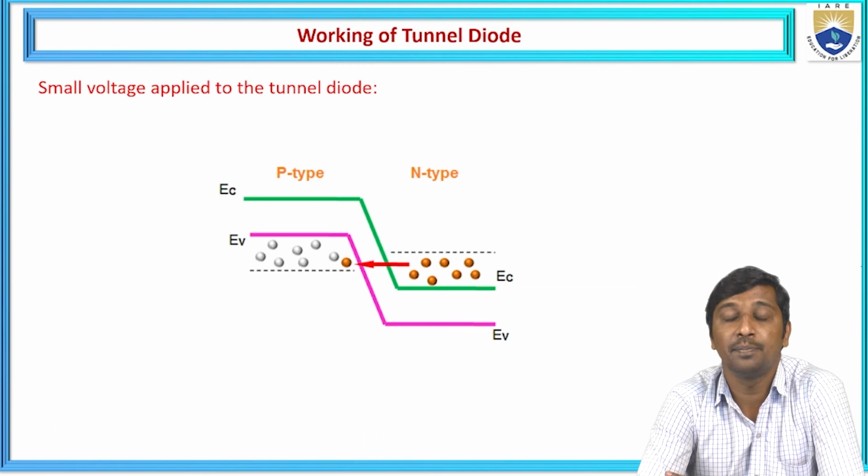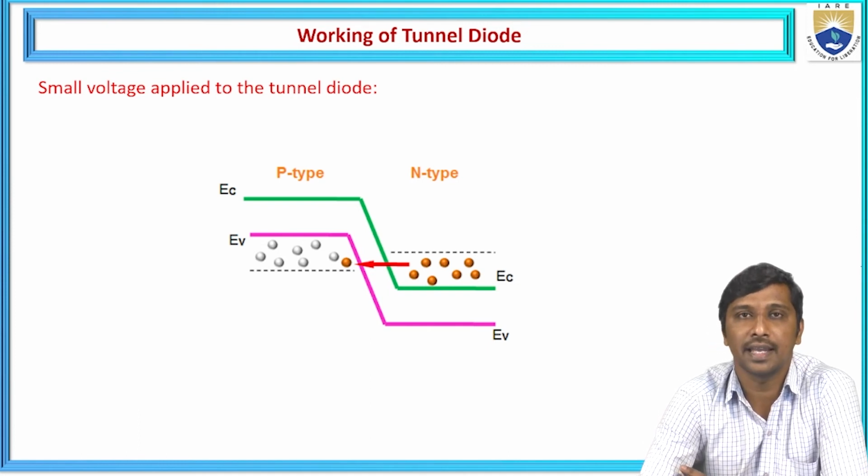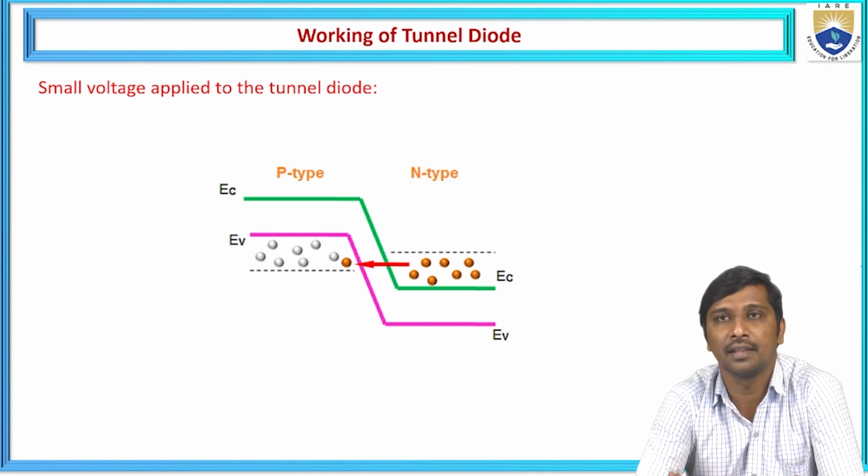happens? The depletion width decreases, hence it allows the diffusion of the charge carriers. If the depletion width decreases, the potential barrier height also decreases. The space charge region is also reduced. Whenever the applied force on the charge carrier is higher than the space charge region voltage, it diffuses the charge carriers from one region to another region.